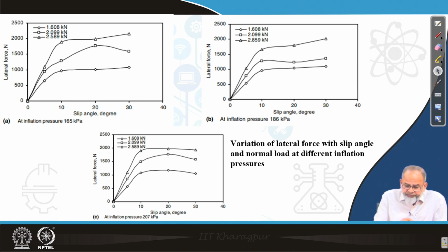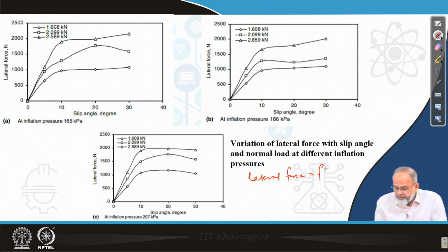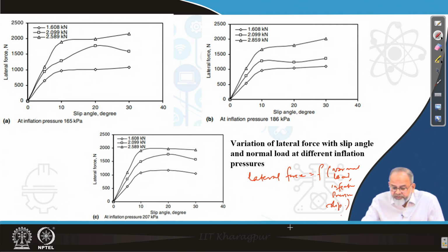So, from these three figures, what we can conclude is lateral force is a function of normal load, a function of inflation pressure, and slip angle for a given tire and in a given soil condition. That is to be taken. Otherwise, it is also dependent on soil condition.